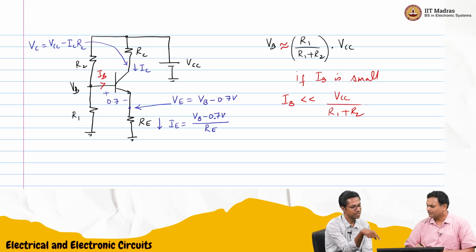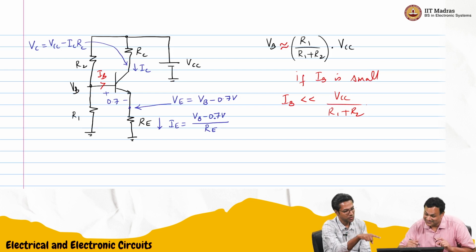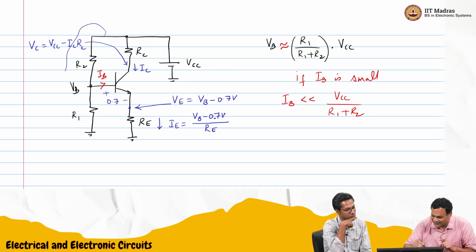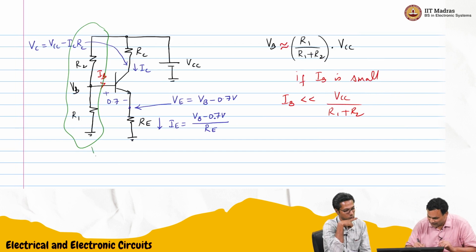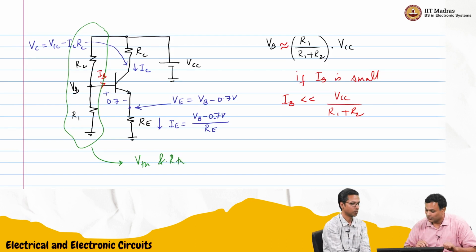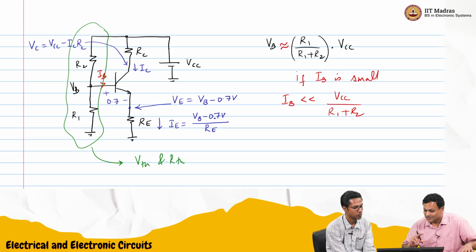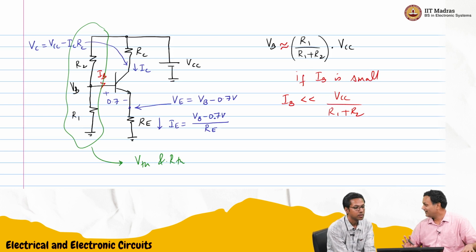So if we Thevenize that portion, we'll create a Thevenin equivalent for that portion, just for the understanding. So here it is not just VB. You now have VB in series with some resistance, which is what we want to find. So open circuit voltage and Thevenin resistance.